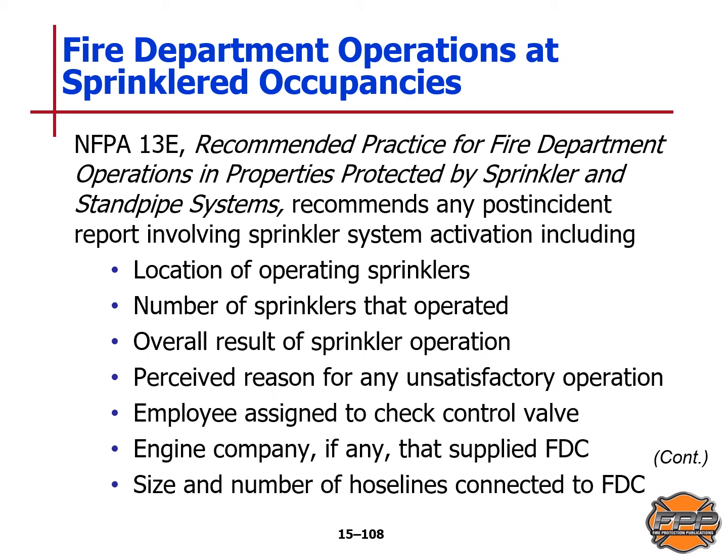NFPA Standard 13E, which is the recommended practice for fire department operation in properties protected by sprinkler and standpipe systems, recommends any post-incident report involving sprinkler system activation include the location of operating sprinklers, the number of sprinklers that operated, the overall result of sprinkler operation, the perceived reason for any unsatisfactory operation, the employee assigned to check the control valve, the engine company, if any, that supplied the FDC, and the size and number of hose lines connected to the FDC.